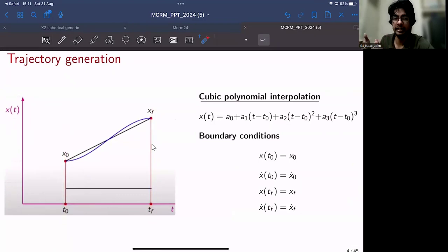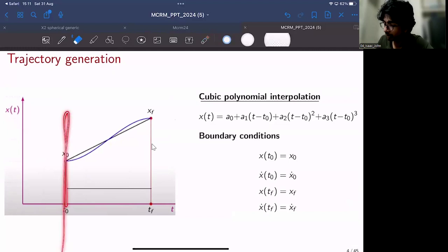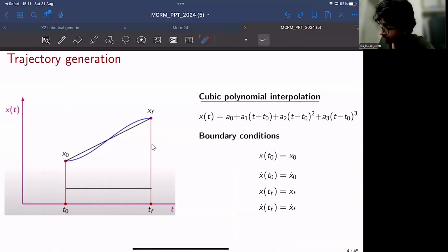That is not desirable in a robot, with sudden or steep accelerations at the beginning and at the end. It is never a good idea to plan something like that, because it can cause damage to the robot and the controller electronics. It may not be good for the motors either, as they may try to draw even more current because of this sudden demand of acceleration.